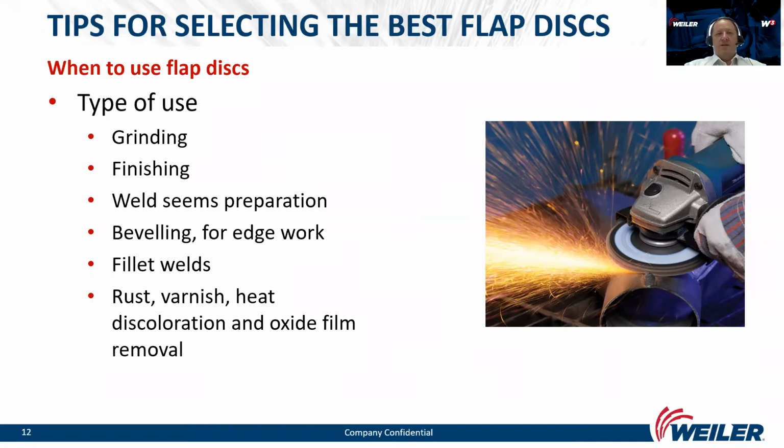Flap discs are normally used for grinding, finishing, weld seam preparation, beveling, and for edge working, for fillet welds, for rust, varnish, heat discoloration, and oxide film removal.